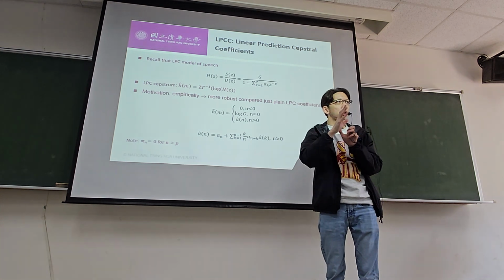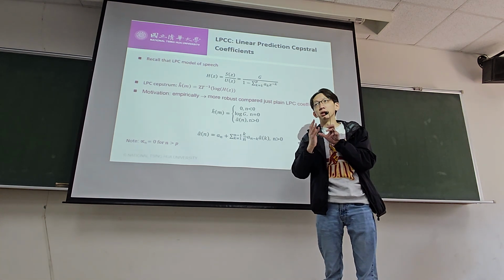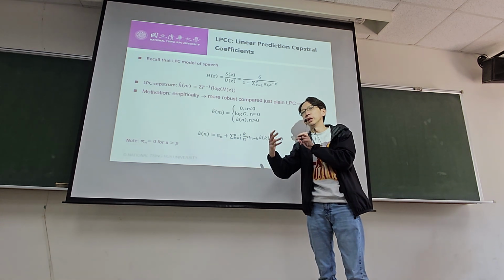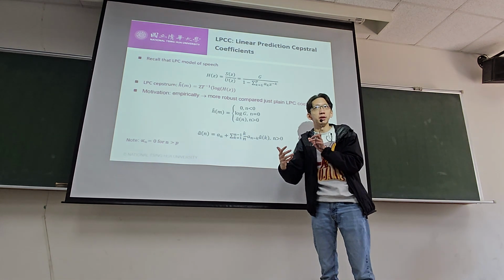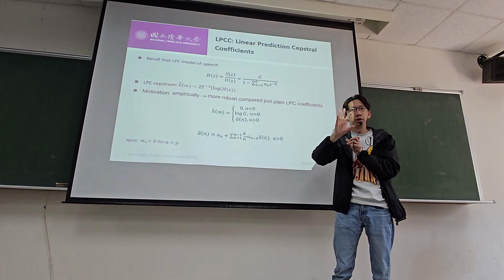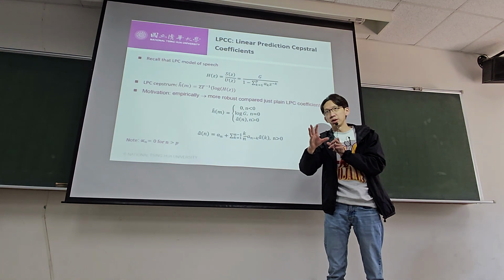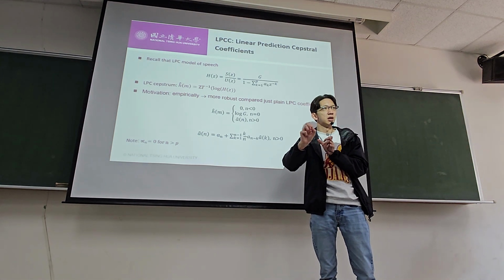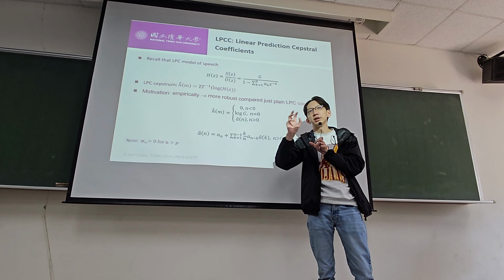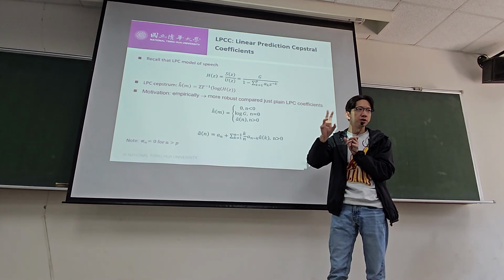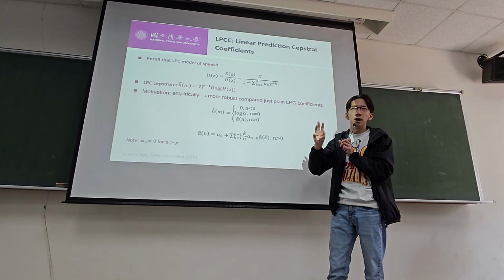We start with the speech production source-filter linear model. With that knowledge of speech production, we know how to derive mathematical formulas. LPC is one particular way to get the filters. Cepstrum analysis is another particular way to get the filters. Smart engineers start putting things together and say, let's do LPC plus cepstrum analysis. And empirically, usually in automatic speech recognition, the first technology they tested, they found it actually works better.